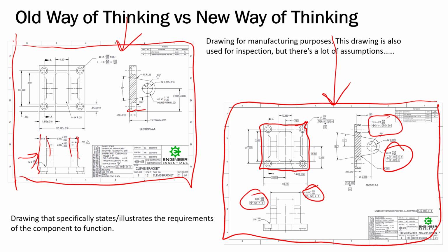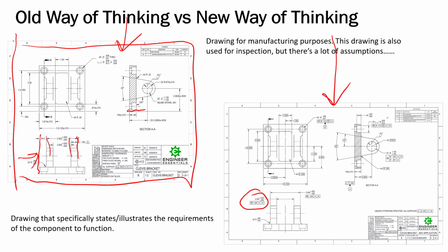It's doing the exact opposite. What it's doing is it's taking the outside profile of this part, or the perimeter, and now locating and orienting it back to the ABDRF, or the bottom face, and then the bolt pattern. So it's bringing it and relating it back to that pattern instead of from a side that is meaningless. So we're able to do that with GD&T and be more clear and specific about it.